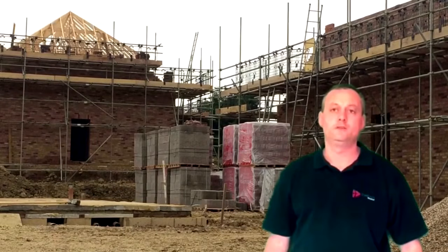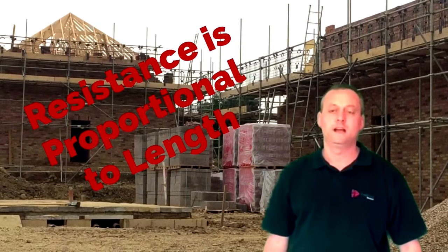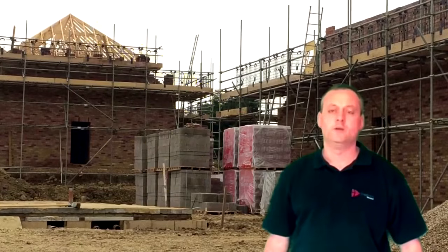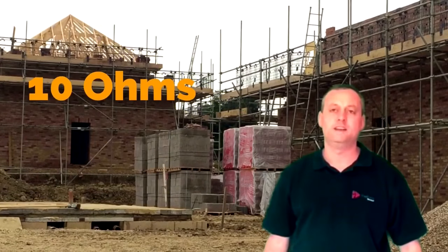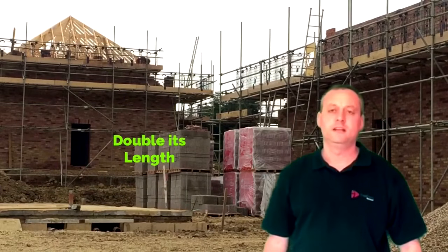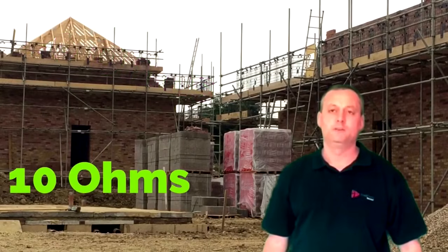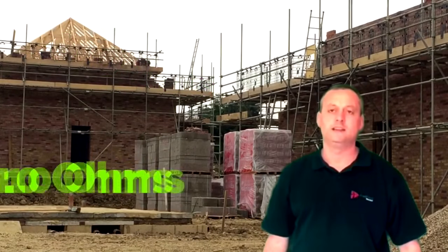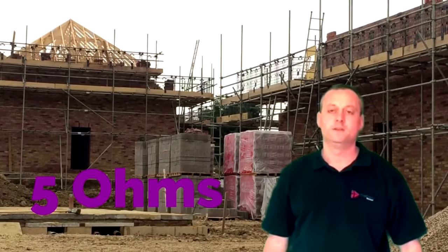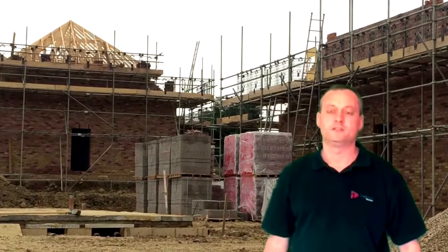We went on to look at two statements that again appear in our exam. Resistance is proportional to length and resistance is inversely proportional to cross-sectional area. So if I have a cable with a resistance of 10 ohms and I double its length and remeasure its resistance, its new resistance will be 20 ohms. If I take the same cable with a resistance of 10 ohms and halve its length and remeasure its resistance, its new resistance is 5 ohms. They are proportional. Double it, double the size of resistance, half it, half the size of resistance.